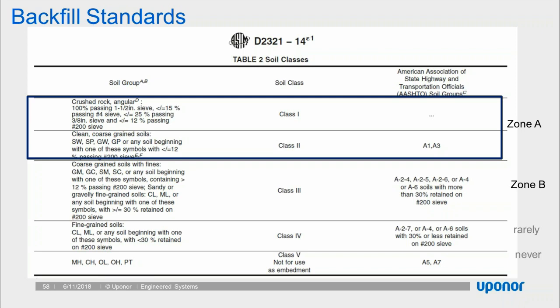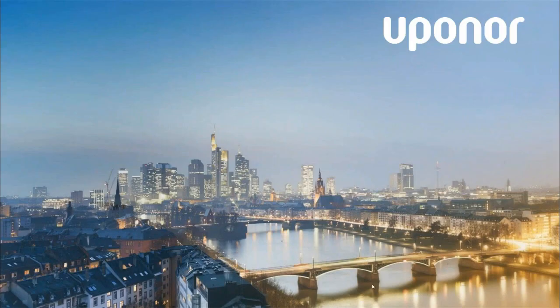And quite often it is okay, or sometimes we have to take other steps, an additional level of compaction or soil improvement to use that existing material, but it is a possibility if import is cost prohibitive. And last, Zone B as defined is a little bit more forgiving. As we said, it's structural road fill. So with that, I will hand it off to Mr. Waymack to talk about some interesting applications of these capabilities.